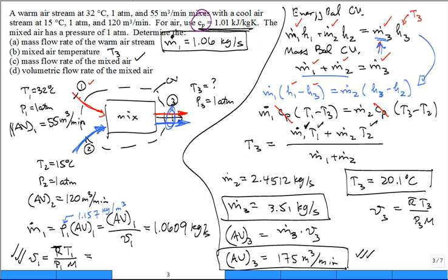Step back a little bit. What is the volumetric flow rate coming in? 120 plus 55 roughly. Hey, did we make an error, or is this just a fluke of good luck? If I added the volumetric flow rate of 1 with the volumetric flow rate of 2, I actually get the volumetric flow rate of 3, good to 3 significant digits. You see that? I went the long way, but is it just random numbers that happen to be that way, or is it actually pretty close that the volumetric flow rate is conserved?